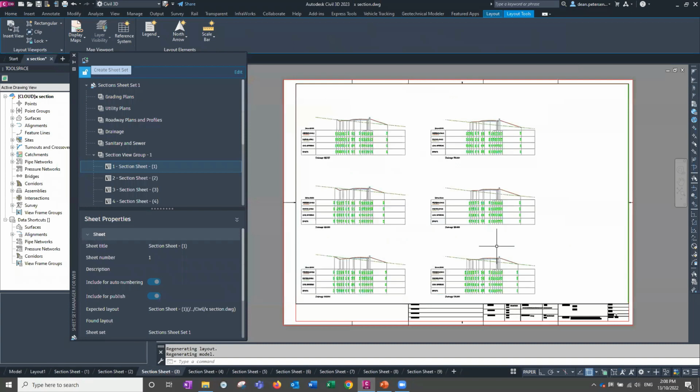So they've made huge improvements to that in terms of the speed of using a drawing that has cross sections in. The regen time's a little bit better, maybe about 25% better for a full regen, but the use of the switching through the layouts is much, much better. So that's actually a really big improvement as well. That was part of 2023.0.